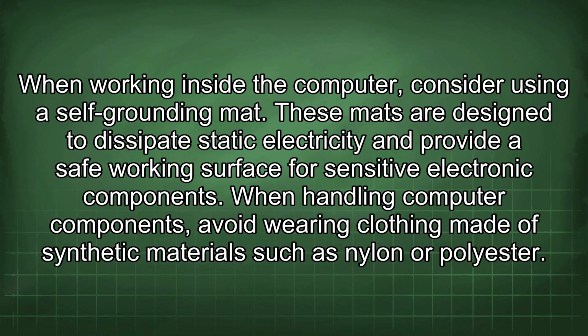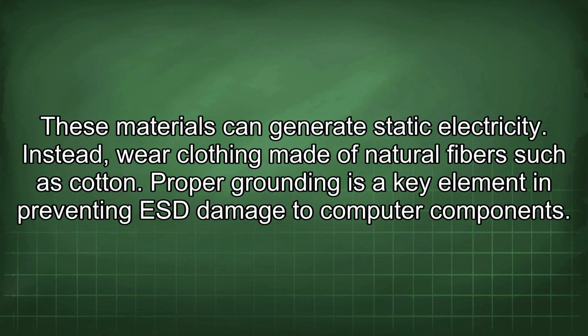When handling computer components, avoid wearing clothing made of synthetic materials such as nylon or polyester. These materials can generate static electricity. Instead, wear clothing made of natural fiber such as cotton. Proper grounding is a key element in preventing ESD damage to computer components.